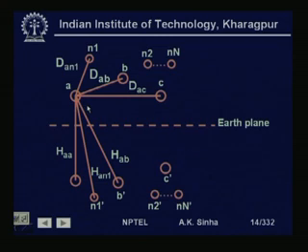So, we are taking an image conductor and using the method of images. Now, we will have, instead of 3 conductors and n neutral conductors, now 6 conductors and 2n neutral conductors in the system, because we have 3 plus n conductors for the neutral as the image conductors also.